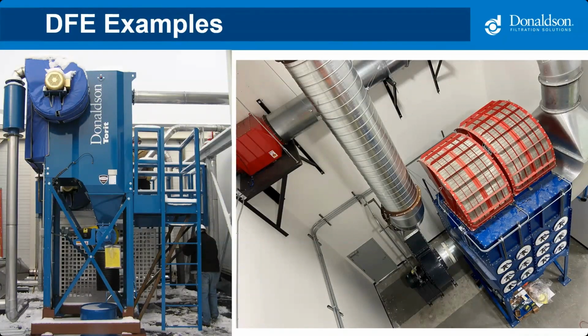On the right, this is a DFE at a nutraceutical facility. And as you can see, this one's inside, and we're dealing with combustible dust. So those red scoops that you see on the roof of that DFE are actually flameless vents. And then the little red box that you got on the left side of the picture is an inlet isolation valve. So if a deflagration occurred inside this collector, those flameless vents are designed to be the weak point.